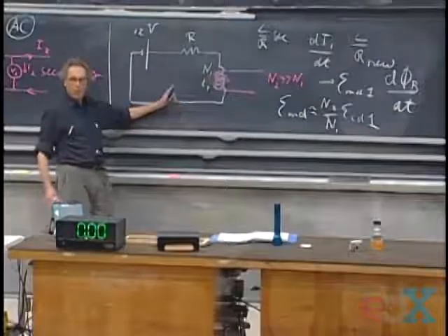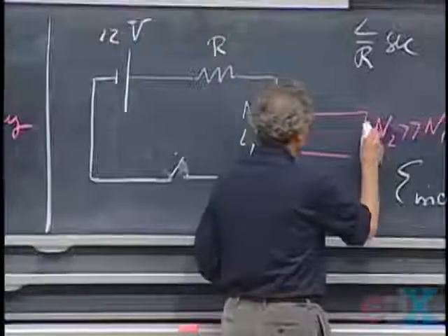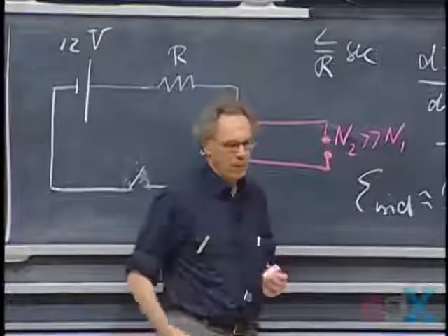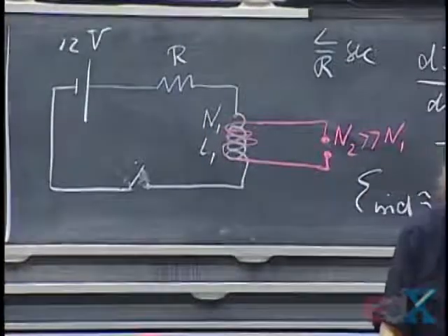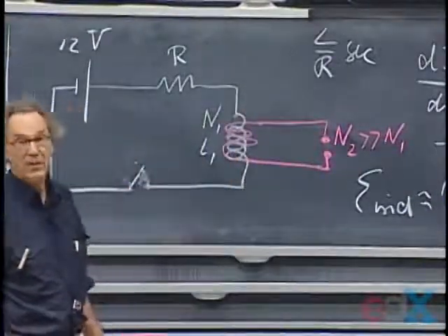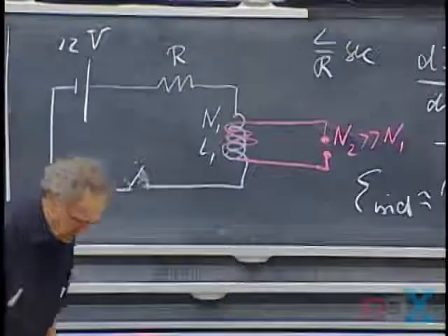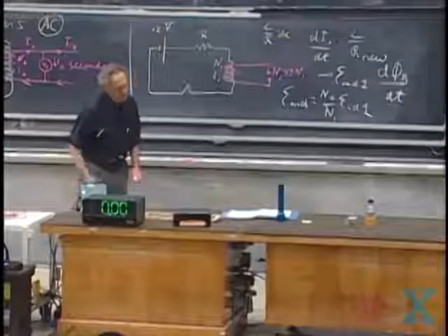And it's only when you open it that you get this pathetic high voltage here and that the spark flies over. And if you run your engine at 3,000 RPM and you have a 4-cylinder, that happens 200 times per second. But it is the breaking that does it. And I can demonstrate this to you.